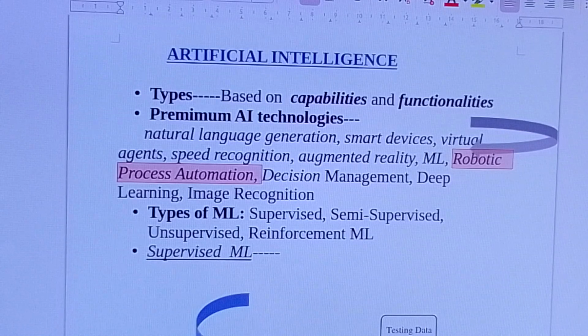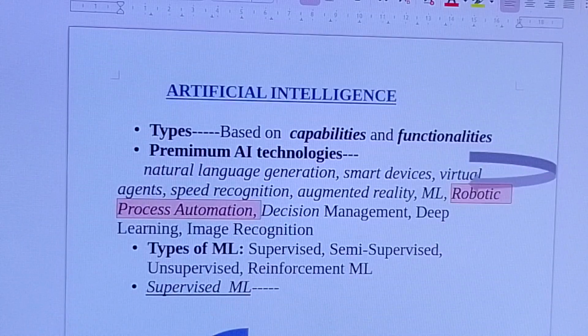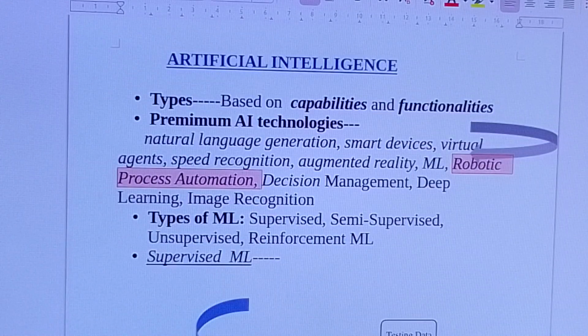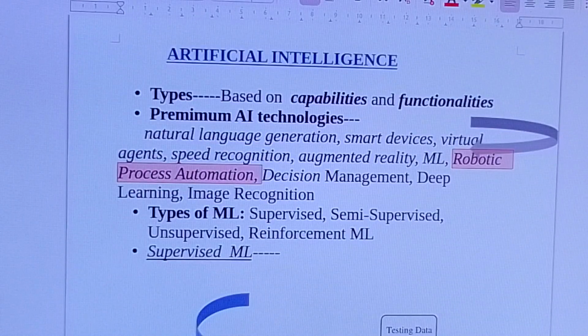Microcomputers are used for programming industrial robots, and different languages have been developed for both online and offline monitoring. Robot software languages include facilities such as subroutines, program branching, interruptions, and signaling to peripheral equipment, etc. Different languages for robot software systems include VAL, used in Unimation robots, SIGLA, all capital, used in Sigma robots, HELP, used in Pragma assembly robots, AUTOPASS in IBM robots, and so on and so forth. At present, there are many different robot programming languages with various important features